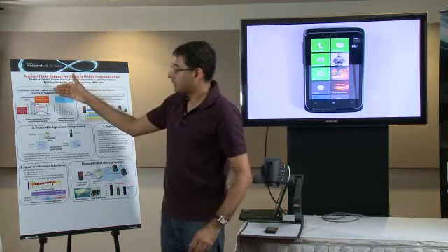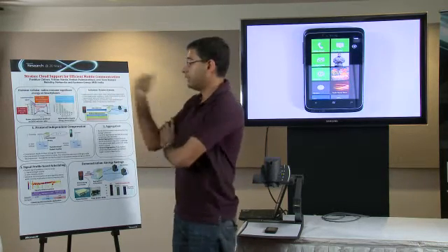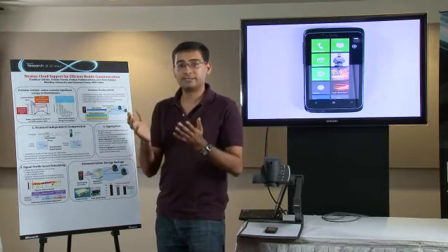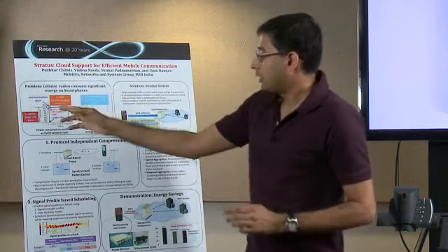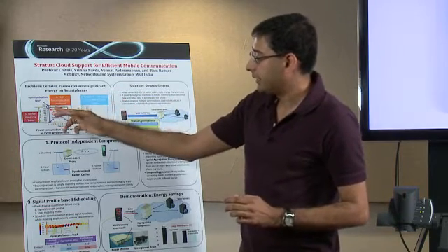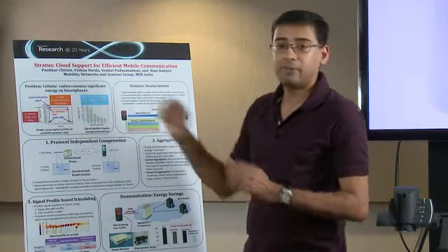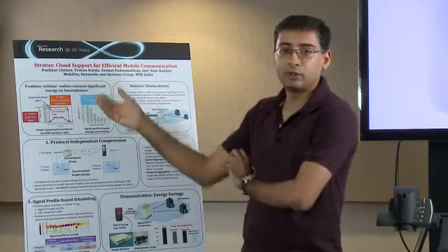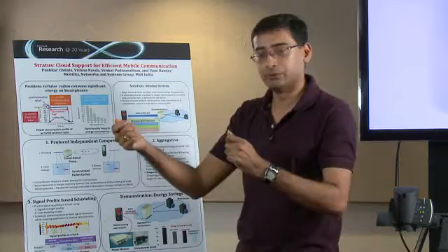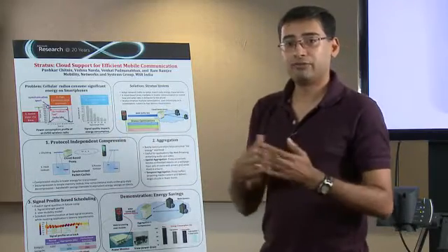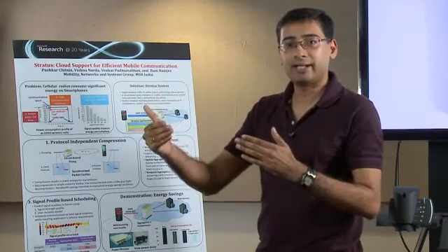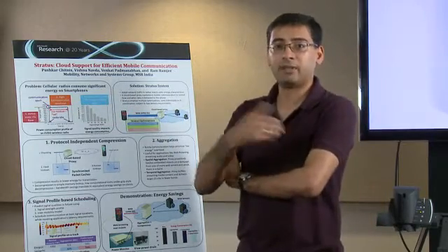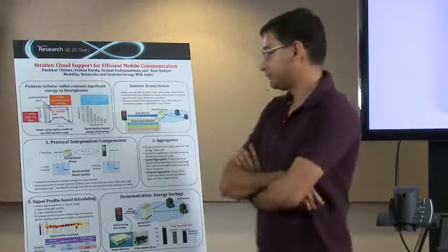The second problem that you see is the communication overhead. These interfaces don't turn on and turn off instantaneously. Notice that even after the communication ended, the radio remains in a high power active state for a long duration of time. So this is the communication overhead for every communication that you do. Now, for example, if you have an application which is doing sporadic communications, the radio will remain in a high power active state for a long time, thus draining energy.